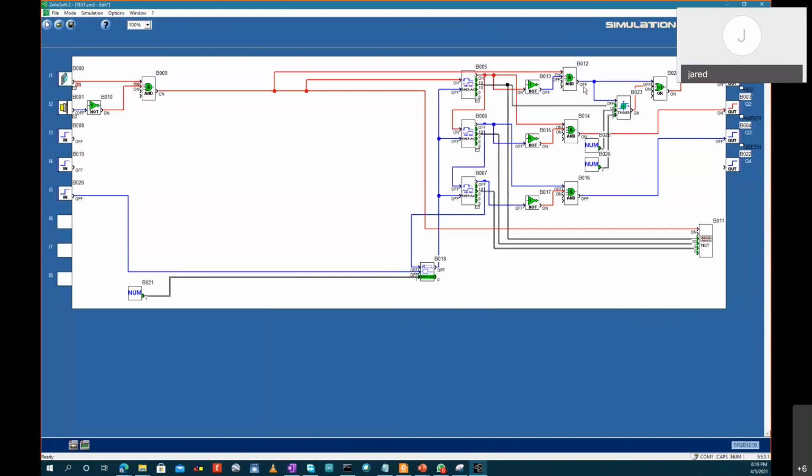So we still have an issue, and that issue we're going to correct, because this one is still on. The reason it's still on is because this logic has not been reset. It's still on because the value is greater than 7. That means it's reading 7, 10. So we are going to stop and edit this logic.